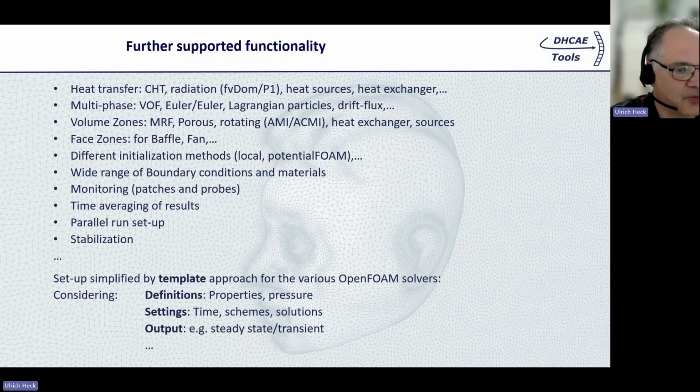But as you probably know, the setup in OpenFOAM can be quite hard, in particular because you have a certain kind of OpenFOAM structure, which is given by the OpenFOAM solvers, and the definitions in the solvers can be quite different. For example, in simpleFoam you use pressure divided by the density. In rhoSimpleFoam you typically use absolute pressure. We try to overcome these different settings in the different solvers by so-called templates. We provide a high number of templates for each solver, which already use predefined settings. For example, for the pressure properties, if you use a pimple solver, we typically have automatic time schemes. And also for the output, if you use a steady-state solver, you typically don't need as much output in comparison to a transient solver.